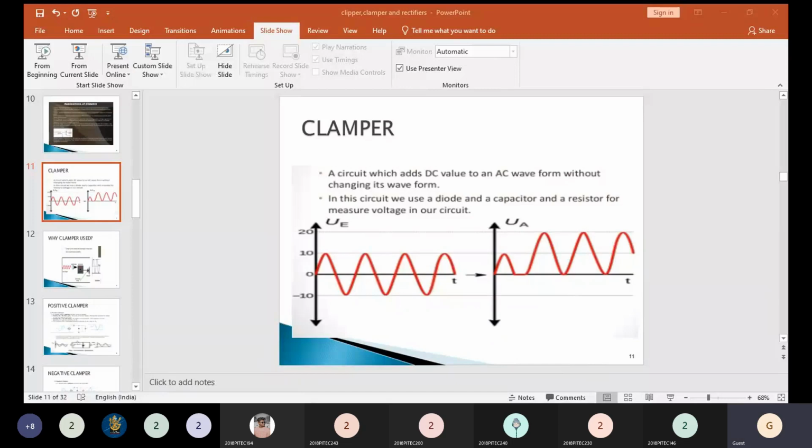A half-wave rectifier uses a diode with a forward resistance. Okay. You have a forward resistance of value RF and load resistance RL. What is your DC current? So the input voltage is given as Vm sin omega t.